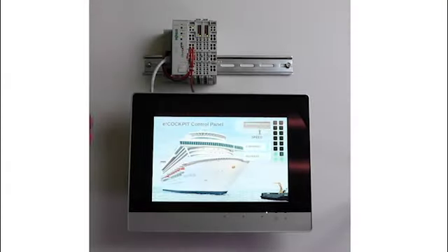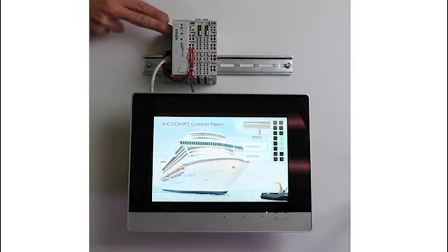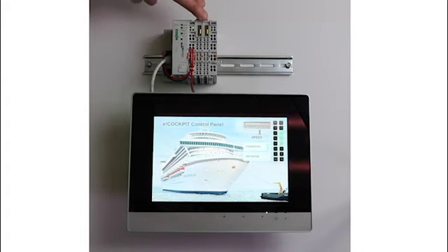This is the 10.1-inch advanced line control panel, which has the capacitive touch glass surface. In this demo, I am showing the EtherCAT master functionality of the panel. I have a WAGO node of EtherCAT I/O that uses the 750-354 bus coupler. This node has a couple of 16-point digital output modules, and these outputs are being controlled by an eCockpit project running on the control panel.